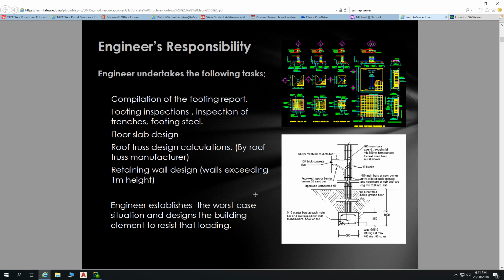And also with all of our footing systems, the location of the steel is important both for strength and longevity. If the steel is too close to the outside of that concrete, it can be subject to moisture and it can rust. What happens when steel rusts is it expands. And when it expands, it pushes concrete out, which makes cracking in concrete, which makes that steel rust even faster, which cracks it even faster, and you get footing failure as a result.